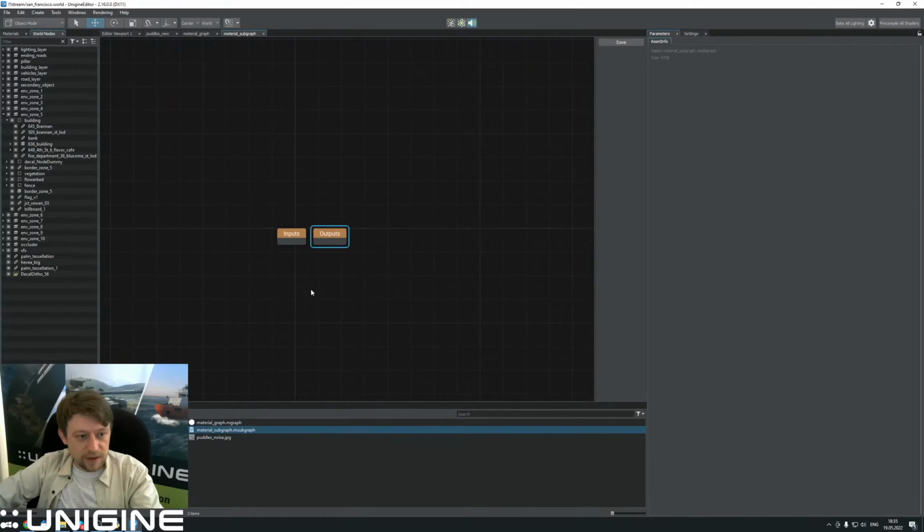It's a separate file which can be used as a single node with custom inputs and outputs. When we open it here, we have by default input and output, and by double clicking here we can add some inputs, choose the type of it and name it, add additional, and the same goes for output.